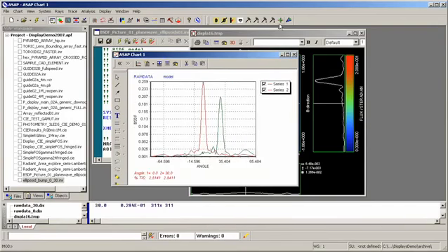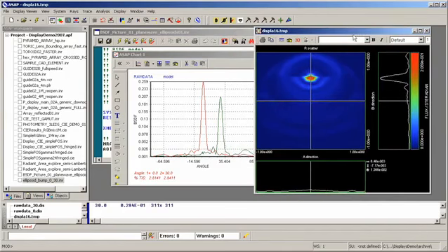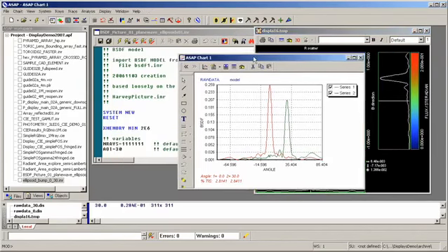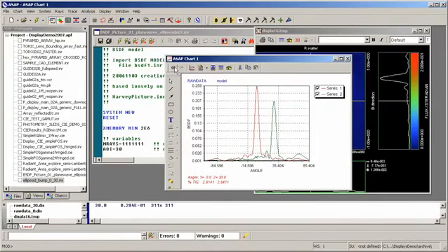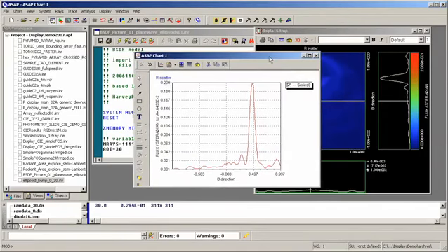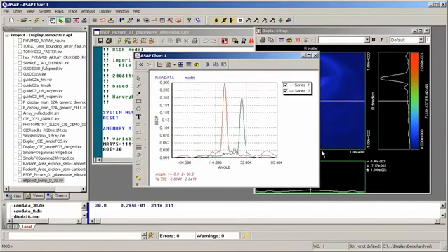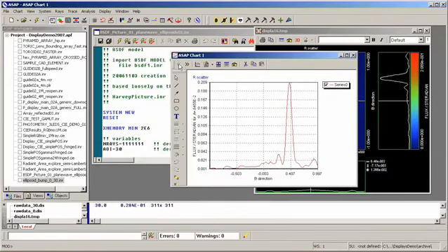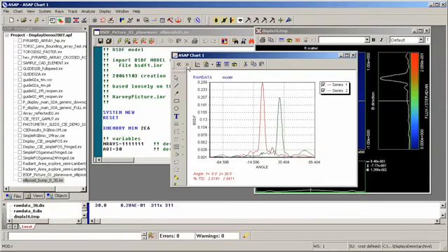So now we see a two-dimensional result of the plotting of the scatter field. We see a plot of the model as imported, and what that means is this is exactly what Lumerical sent us, and this is the actual measured scatter data as the result of tracing rays. So the direct comparison is that this is a 30-degree angle of incidence plot of the actual scatter, and this is a plot of the model.